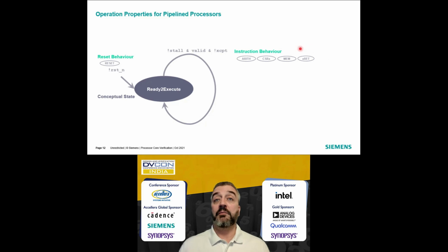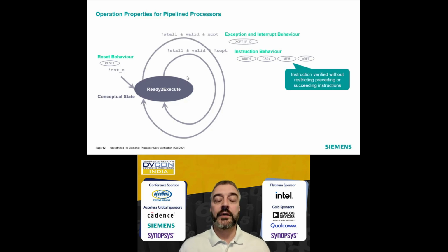And in this case, there's then a bunch of assertions triggering in this scenario. And in this scenario, they're going to verify exactly what we have seen on the previous picture. They're going to verify the update of all the architecture registers and also the traffic that is generated on the data cache.